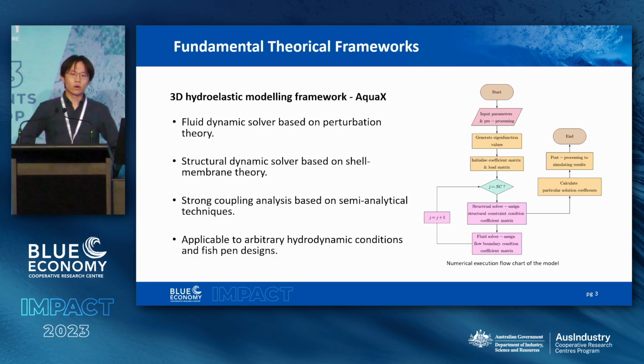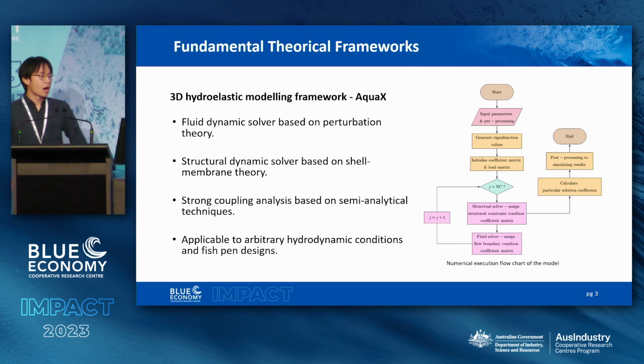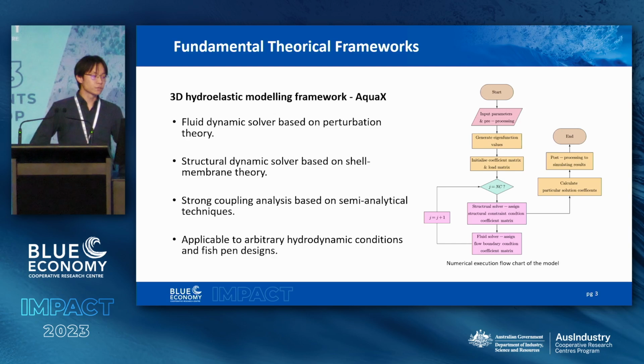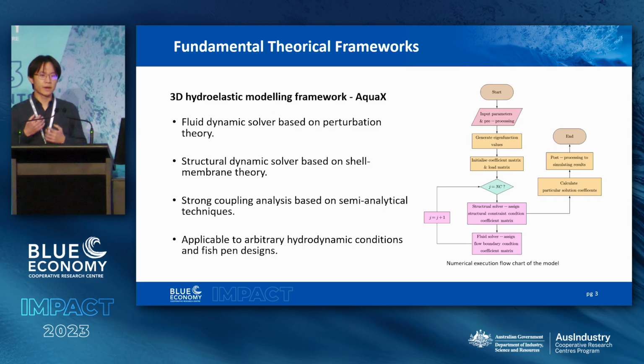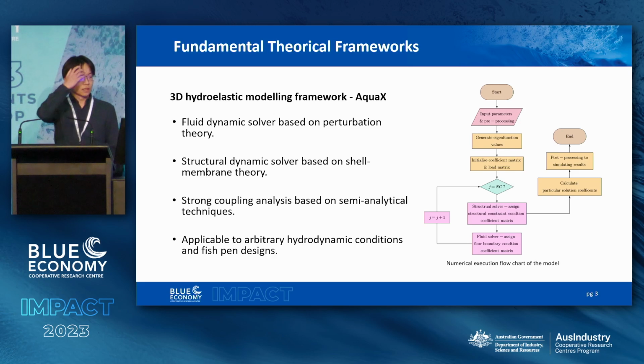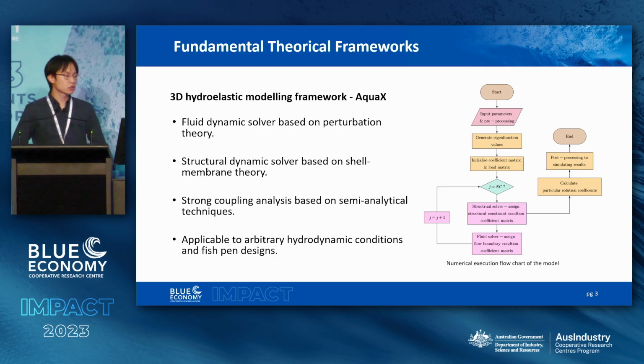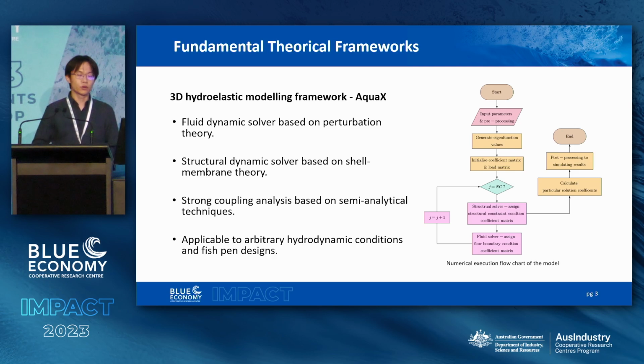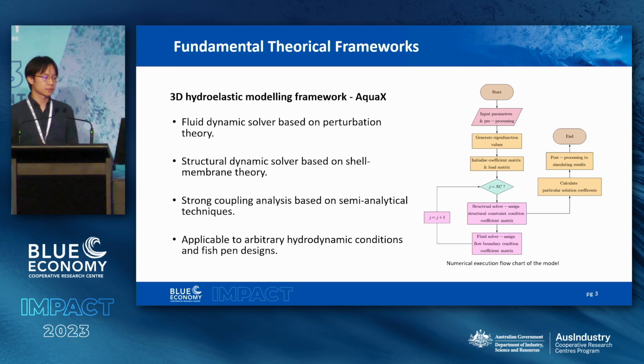To achieve our research objective, our team developed a 3D hydroelastic modeling framework, AquaX. AquaX mainly combines techniques from fluid mechanics and structural dynamics. The fluid dynamic solver is based on perturbation theory, and the structural dynamic solver is based on shell theory. Our model is feasible for strong coupling analysis using semi-analytical techniques, and is applicable to arbitrary hydrodynamic conditions and fish pen designs.